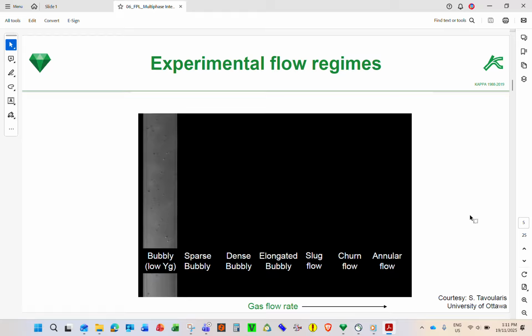And with increasing gas velocity, you may see the difference of the flow regime. Same thing like this: you start with small bubbles, and you have a bigger bubble, collecting the bubbles, become a slug, and sometimes it's not continuous, homogeneous, then it will be like a churn flow, and then the annular is like a mist. So in annular mist, you might not be seeing the liquid content.